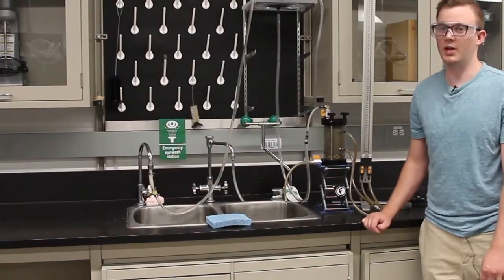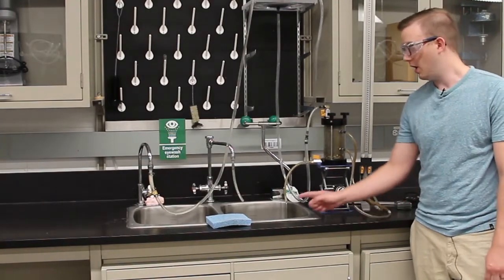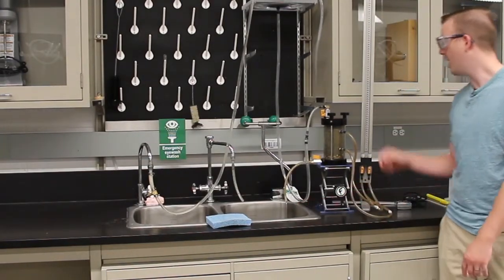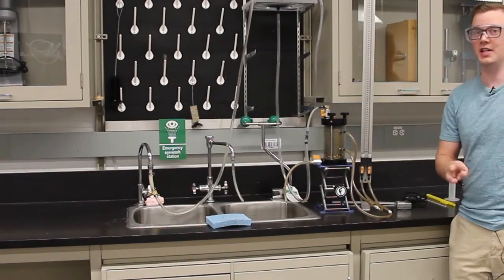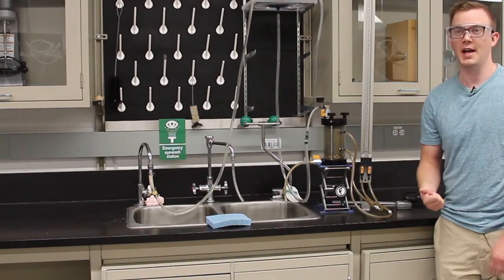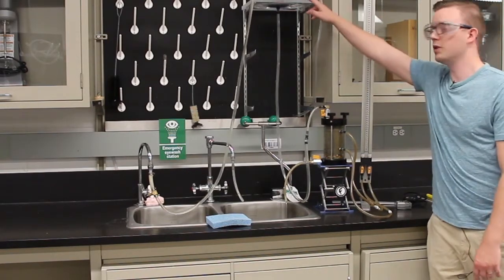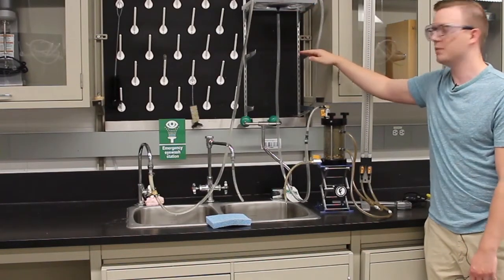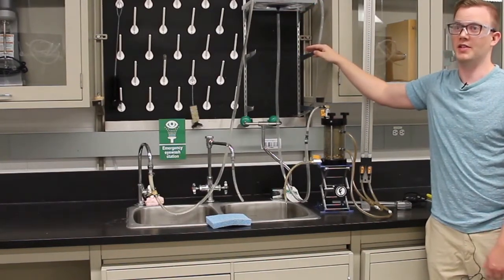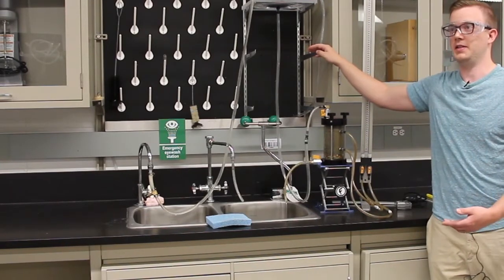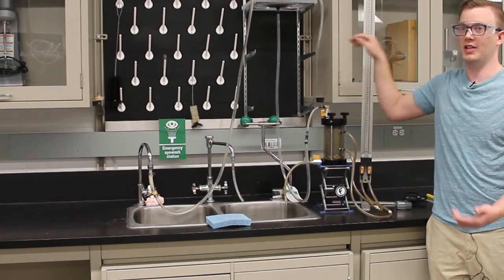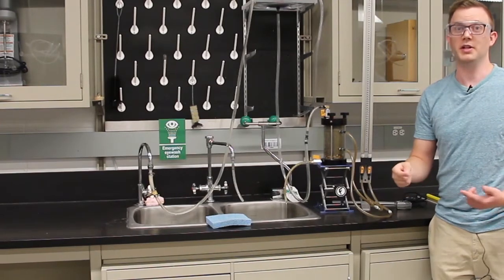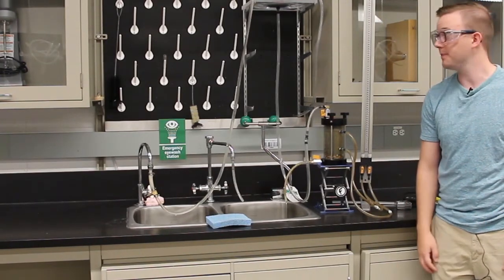All right, so you're going to want to make those measurements 3 times. Water quantity as well as manometer readings, you're going to do that 3 times, as well as the temperature readings. And then you're going to lower the constant head tank one more level, and you're going to repeat the process. So you'll be able to get different values at different gradients, and this should allow you to determine what your permeability is, at least in the downward direction.